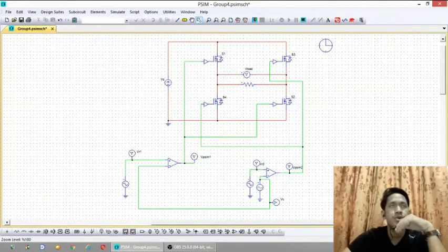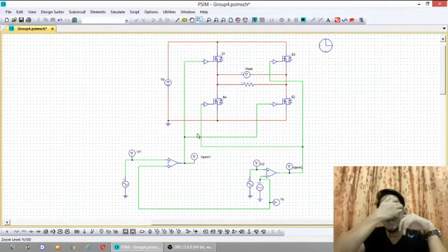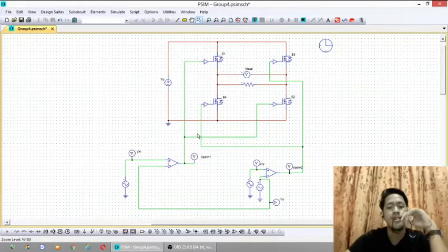lines. The output voltage waveform of the ideal inverter should be sinusoidal. However, the waveform of the practical inverter is non-sinusoidal and contains harmonics. So in this simulation diagram, the triangular carrier waveform is compared to the two reference signals, which are the positive and the negative signal. The basic idea to produce the SPWM with unipolar voltage switching is shown in